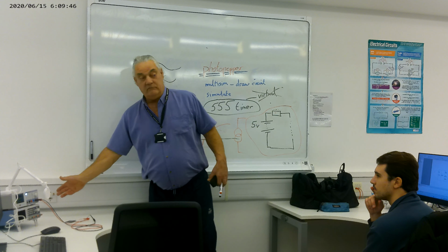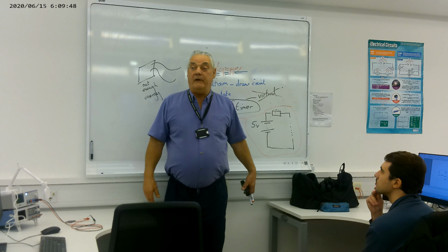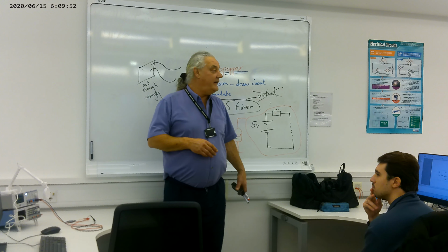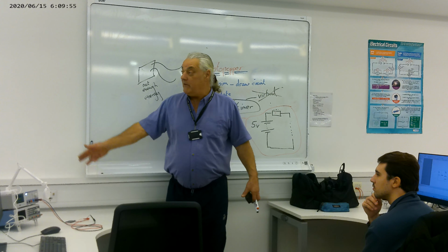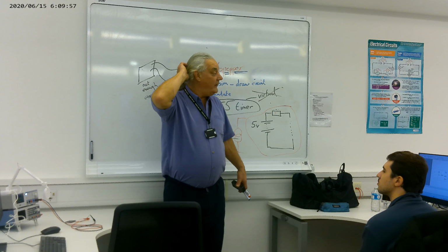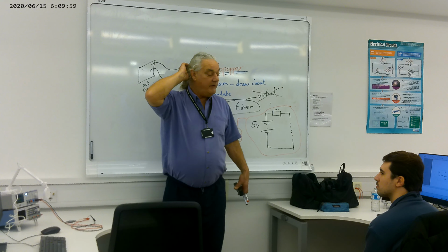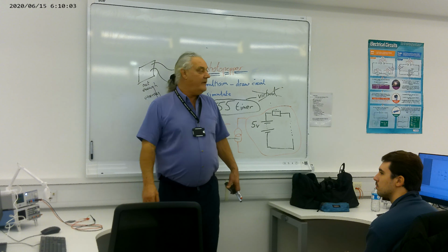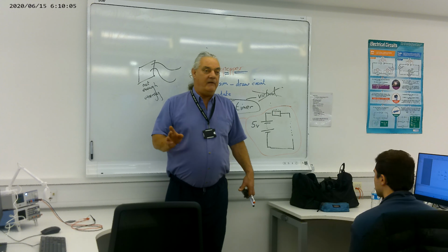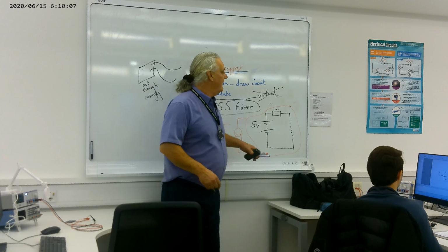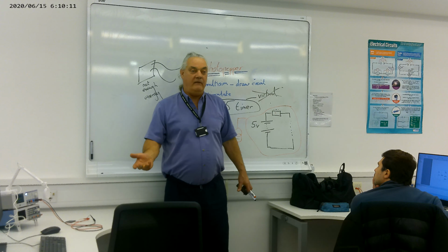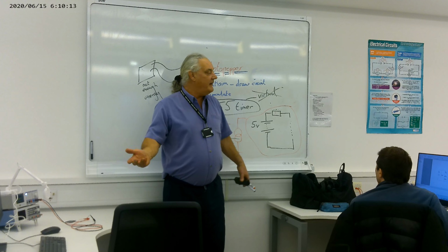And just what I call quiescent inside this room, the background radiation, because that's what light is, it is radiation. So we've got background photons bouncing about off all the walls and everything. Our solar panel is picking up enough to convert that to 2.7 volts. It's useless because this value of resistance that we're going to model inside here is huge, 100 megaohms probably.